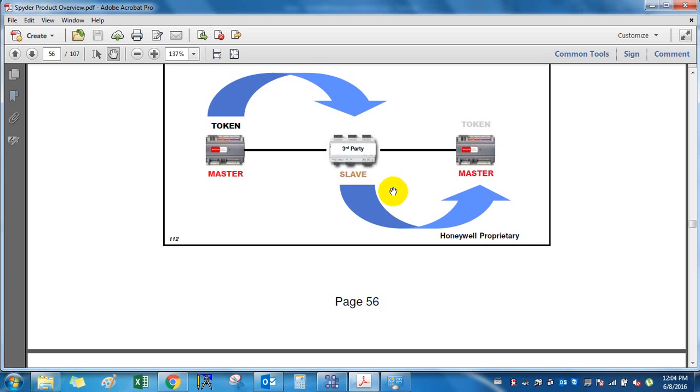And this is your Modbus device. If you see your JS, it has one RS485. This Modbus meter is connected to this RS485. These pins are connected here. It is polarity sensitive. This is positive, negative.